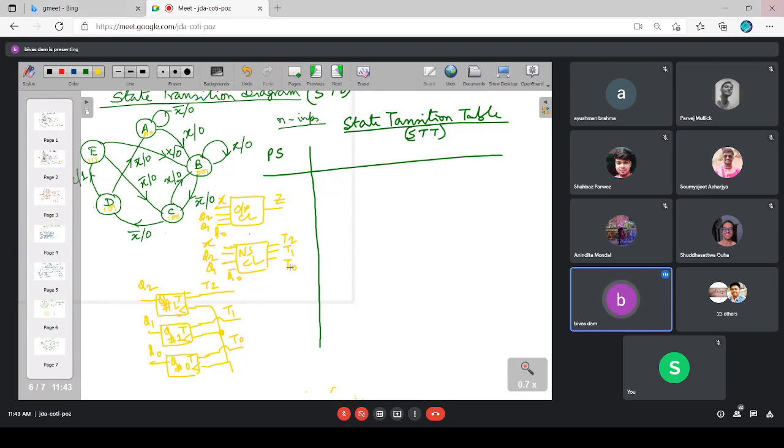But if you had used D flip-flops in place of the toggle flip-flop, in that case these D2, D1, D0 will be directly your new Q2, Q1, Q0. Yes, sir. So in that case, I could have said that the next state combination logic outputs are the next states, because the next state values are the D2, D1, D0 values itself. Is it not?